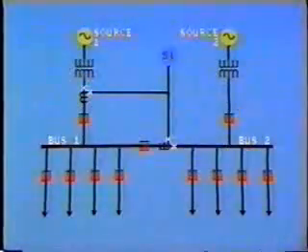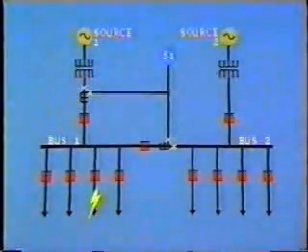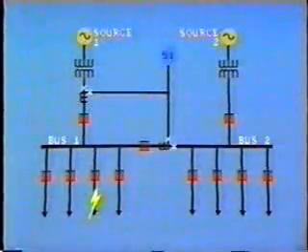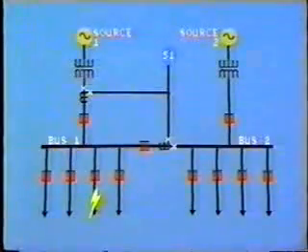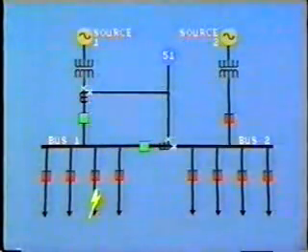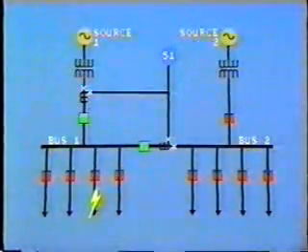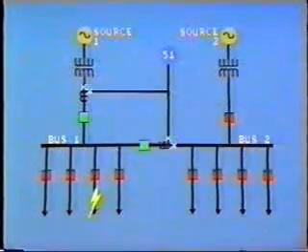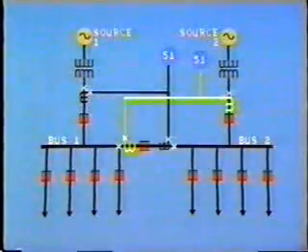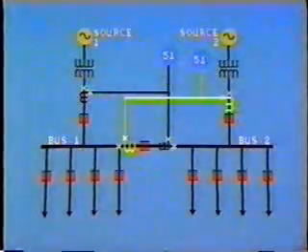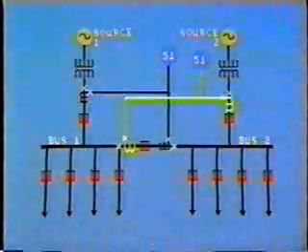This protection will also operate for a heavy fault on a bus 1 feeder, which fails to be cleared by its own breaker. The system therefore operates as backup, and the setting of the relay must allow for this. Of course, a similar pair of CTs will be connected to provide partial differential protection for bus 2.